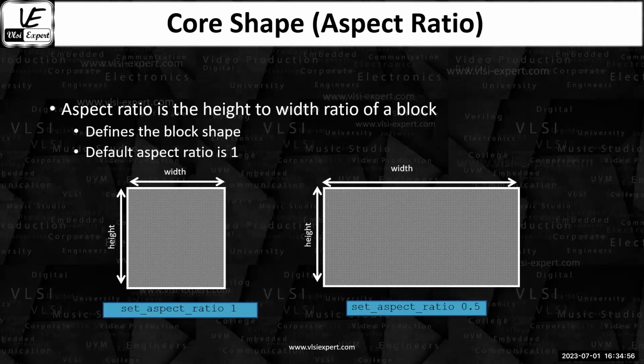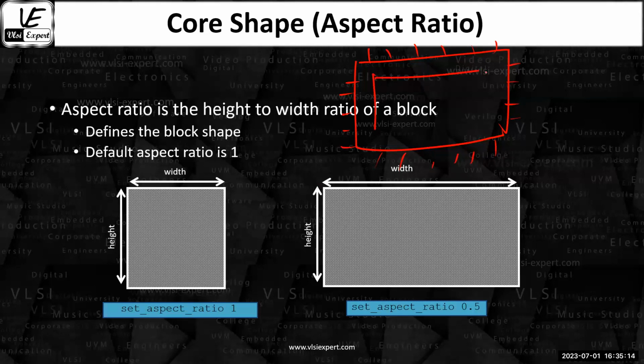Now, in terms of the floor plan, there are two things, the core and the IOs. If I say this is my chip and these are my ports, you are not going to connect these ports with the inside logic directly. You have to create a boundary here.